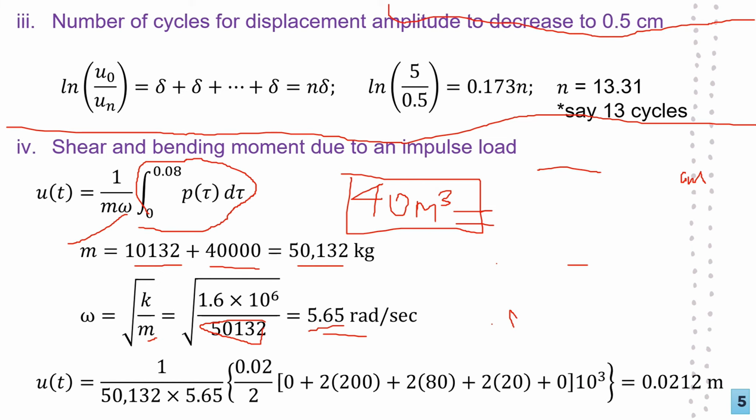So this one I have compressed because I want everything to fit in this slide. So this part, you have the mass 5132, you have the frequency. Then here, this duhamel integral, how to evaluate it numerically, I just use the trapezoidal rule. So the trapezoidal rule, you had this. I want to place everything here. The time interval is 0.2.